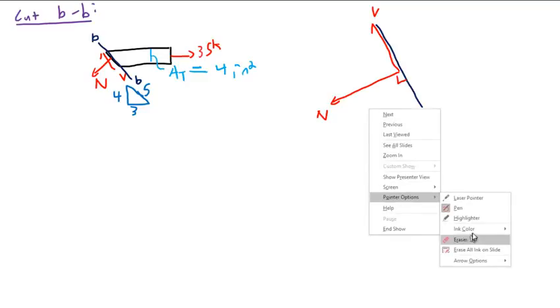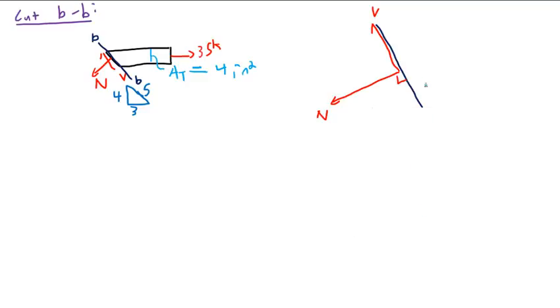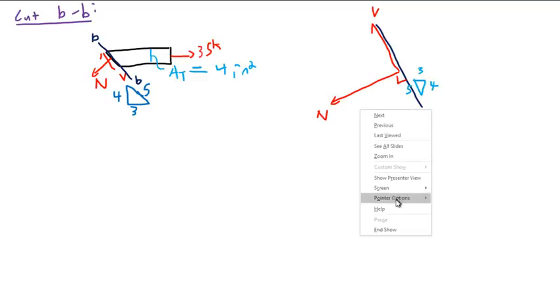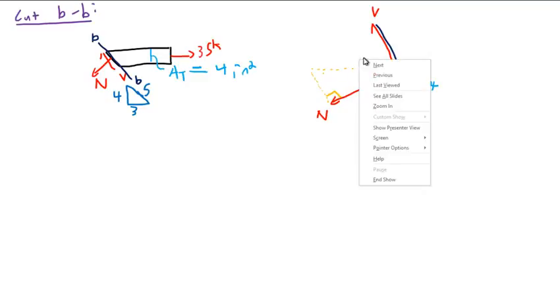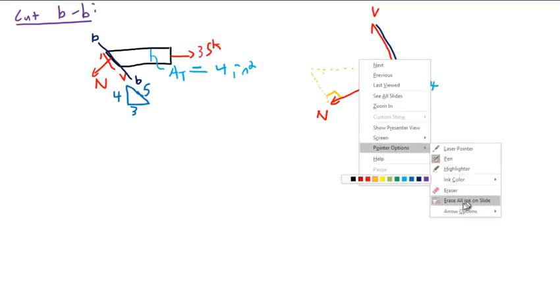And this is the same 3, 4, 5 triangle. And then if I work through some trig here, I'm going to have the horizontal angle here. So let's consider this right angle here, like so. Basically, these will come together to make the 35 kip force.